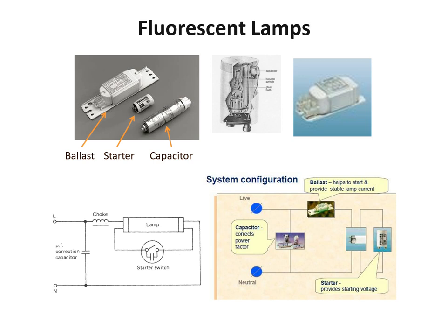When you're dealing with fluorescent lamps and you need to replace it, you'll find that most of the time the lamp is still functioning. It is the starter, the ballast, and the capacitor that has fused or worn out that you need to replace. Back in those days, you could purchase the starter and the capacitor separately from the shops and do a replacement.